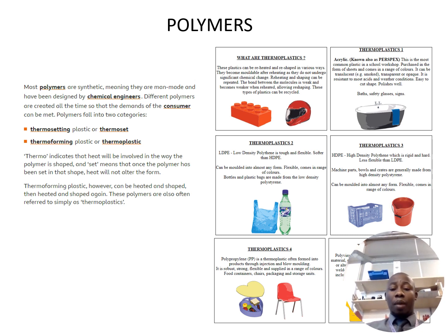The next one is polypropylene. It's another example of a thermoplastic that can be reheated and molded multiple times, and we see this one being used a lot on the seats that we sit on in school, but also on any food packaging, for example margarine and butter containers. And then the last one would be PVC, and PVC is mainly used on drain pipes that we find at home or on any general buildings basically.